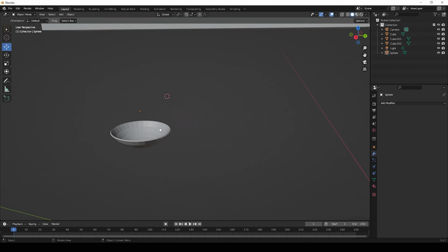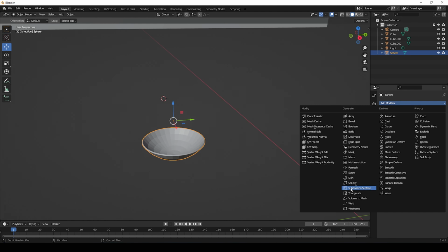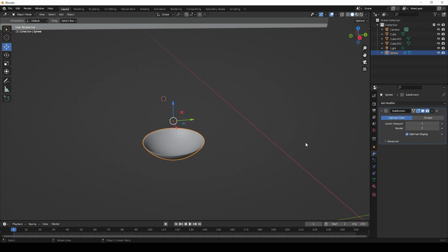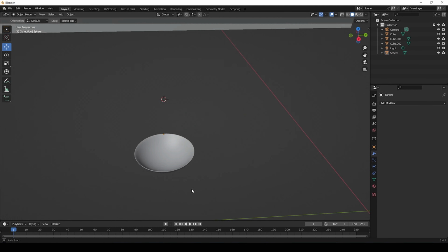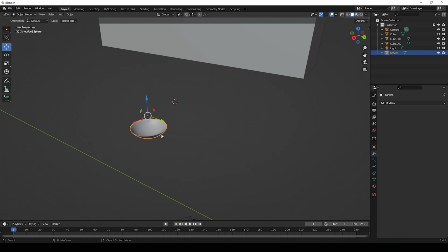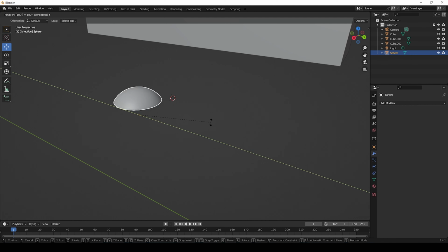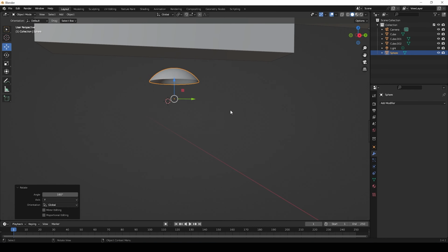And now we've got a parabola that has some depth, but it's looking super 1990s polygonal. So I want to take some of those polygons out. I'm going to click the object again, add another modifier, and we're going to do subdivide surface. This basically takes your polygon and cuts it into smaller polygons to give you more resolution. So we'll do that 3 times. That's already looking pretty smooth, and there you go. We've got a nice smooth parabola. Next thing I want to do is rotate this object around the y-axis so it's facing down, essentially in this frame towards the earth. So we'll type R, then Y, and then 180. It's just going to turn our parabola upside down.